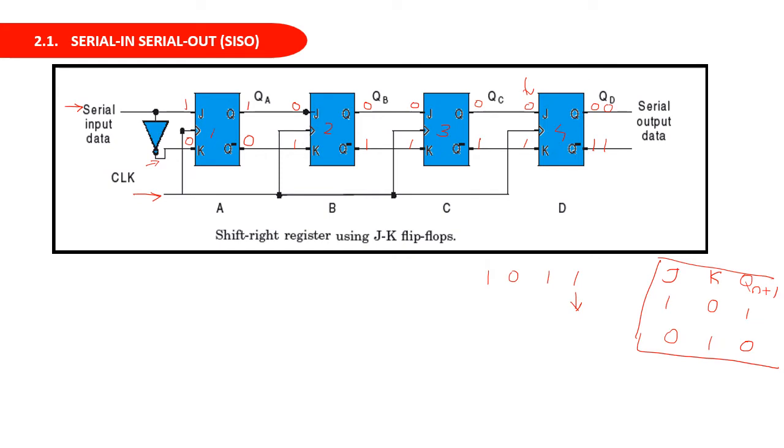Now when the next clock pulse comes, the next data to be transferred is again 1. So what will you give? You will give 1 to the J terminal, so 0 will appear at the K terminal. At that time, when the first clock pulse comes, the output of the first flip-flop is 1 0. So that will be fed as the input of your second flip-flop.